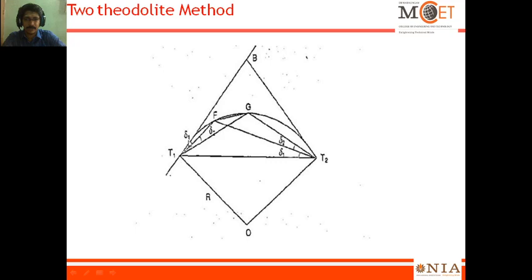The accuracy and smoothness of the curve can be achieved very neatly using two theodolites, but it is a time consuming process. But when the curve should be set very precisely, this methodology is adopted in many major projects, right? Even for curves in bridges and flyovers, they check this changeover very keenly. If there is any mistake, the travel or accident issues will be more. So this is one of the advanced levels of Rankine's method.